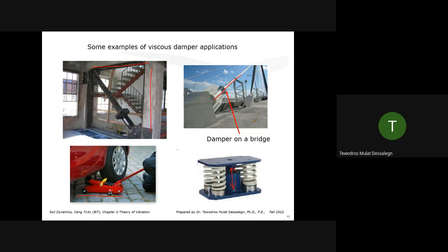But for our geotechnical section, when we say damping, it's within the soil particles. You can have permanent deformation in the soil, particles sliding one over the other, friction loss, all that, or settlement. That will introduce the damping, or the energy dissipation.